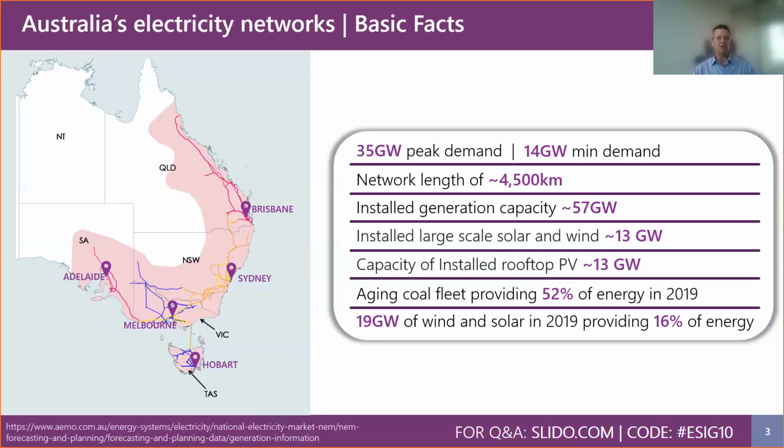There is no day-ahead mechanism to the NEM's dispatch, and AEMO uses pre-dispatch forecasts to manage expected reserves for resource adequacy purposes. Operational forecasts are provided through AEMO's solar and wind forecasting systems, the ASEFS and the AWEFS, although AEMO has also been running self-forecasting trials for renewable generators in cooperation with the Australian Renewable Energy Agency over the past couple of years, and this is primarily to assist renewable generators in managing their causer pays payments, which are penalties applied if you don't meet dispatch targets.